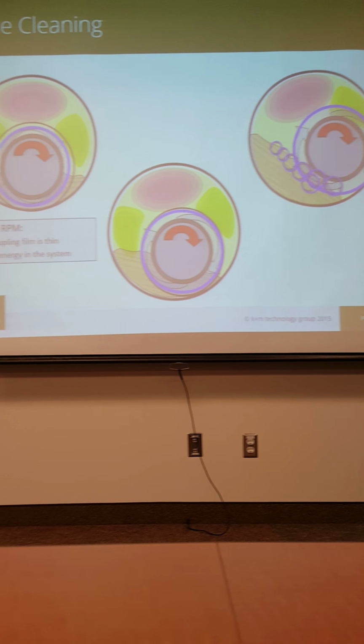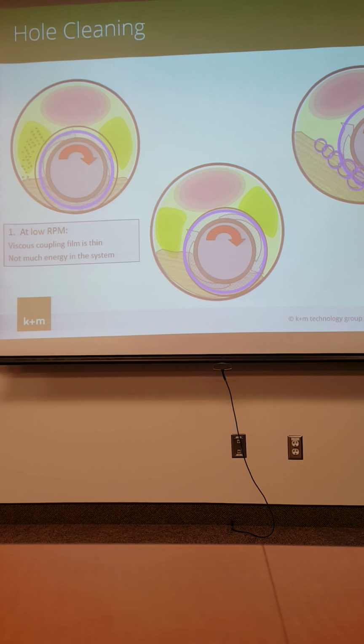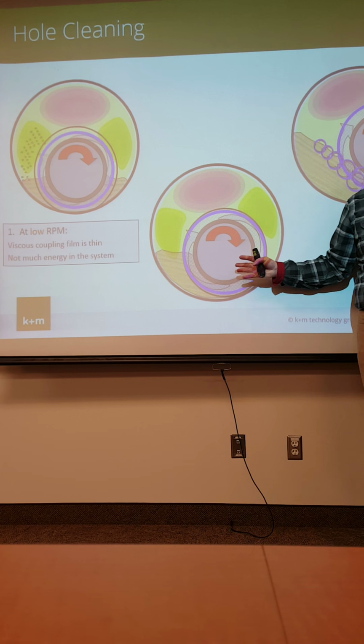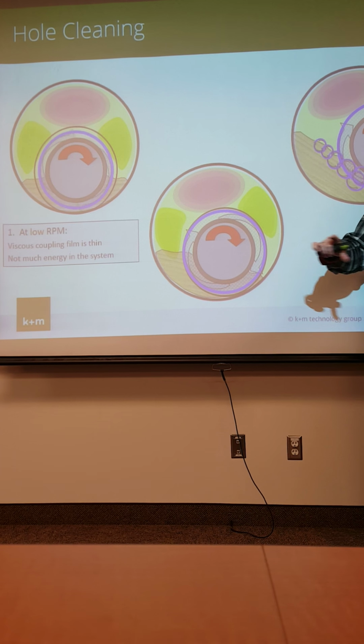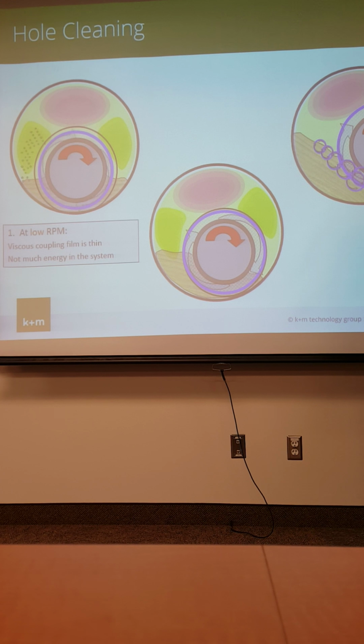We patented the idea, in fact my name's on a patent, of roughening up the drill pipe to try to enhance the viscous coupling layer. So we experimented with different surface coatings to try to decouple or enhance just how much of this is going on, and we definitely found that there is an impact depending on what surface finish you put on the pipe. Just didn't go anywhere, so yeah.